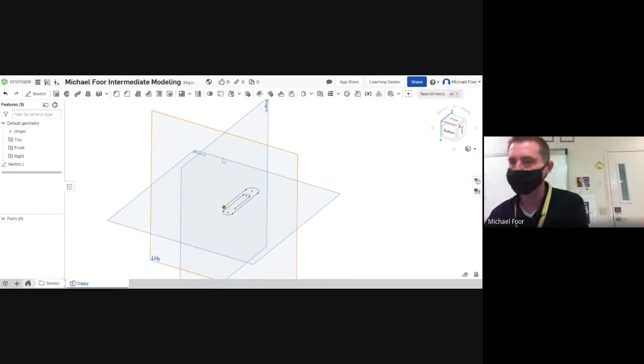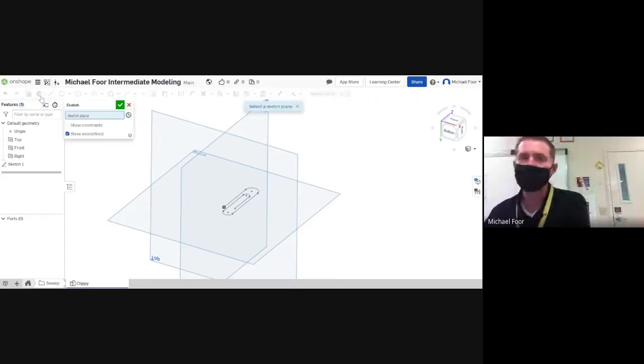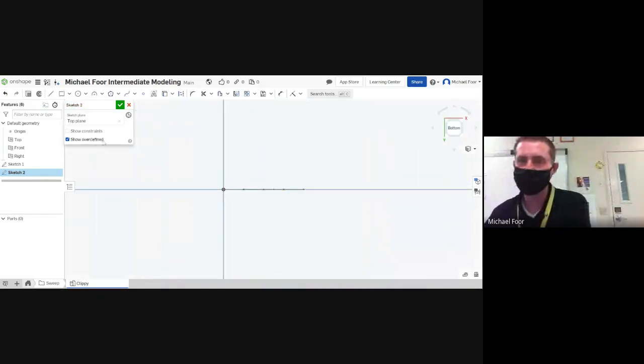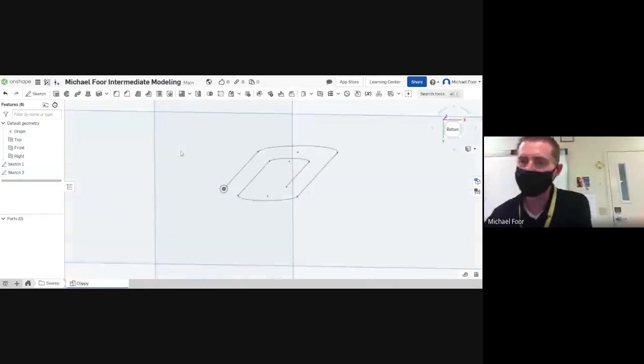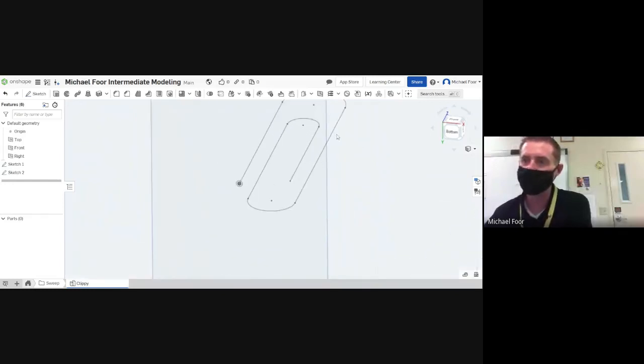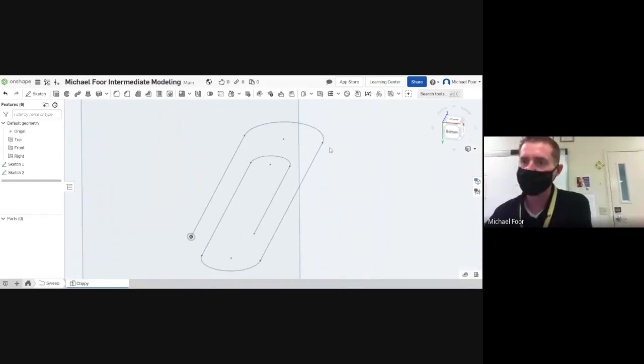So I want to create a sketch on the plane that is perpendicular to my paperclip. Okay, so get sketch right there. And then we want to lock onto this origin because we want this to be attached to the same point that's at the base of the paperclip. That's it right there. So you can kind of see, probably like I said, where this is going. So create a sketch on that perpendicular plane, make a circle, mine was 0.05, and then we'll